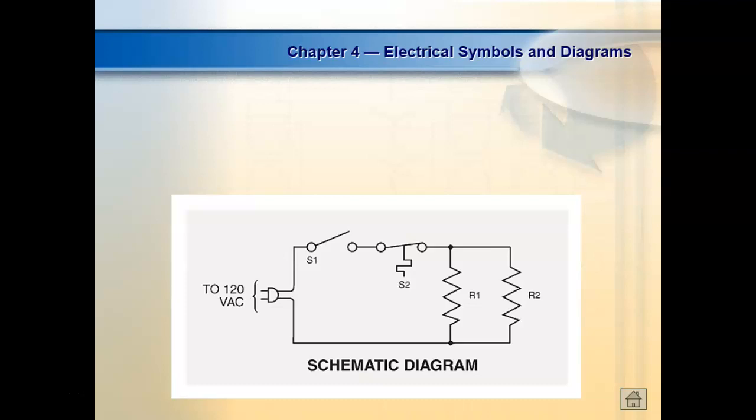No, it's just an enclosure, just a box. So this would be like your relay module under your car. It's all inside of what? A box. So a wiring diagram would try to draw everything together and put it inside the box, while a schematic would draw it the way it operates, right?